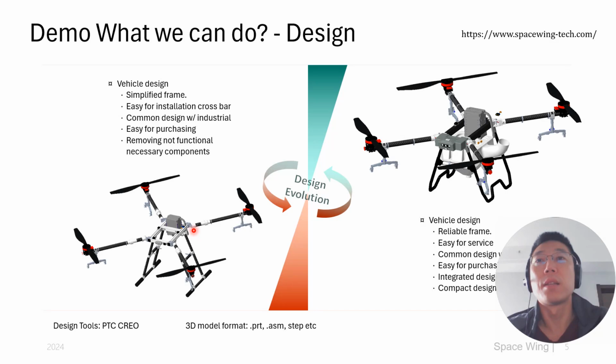We need to design concepts that we can buy from the market. We don't need to kick off new tooling, and we don't need special tools to assemble and build the prototype. It should be easy for purchasing. We need to define the prototype's target very clearly, and we can remove non-functional, unnecessary components.